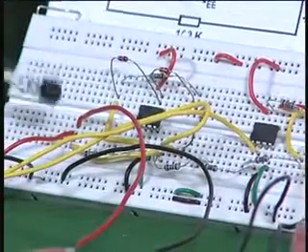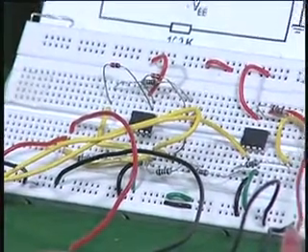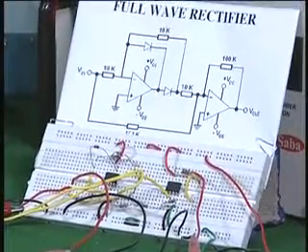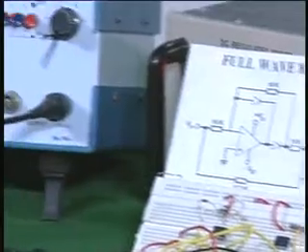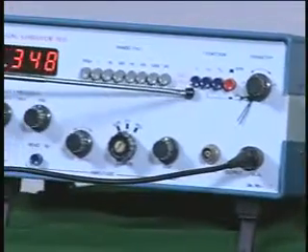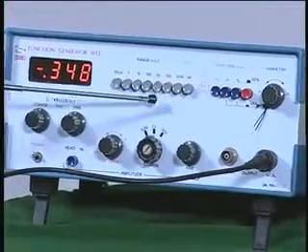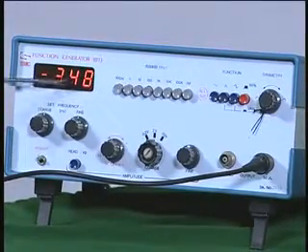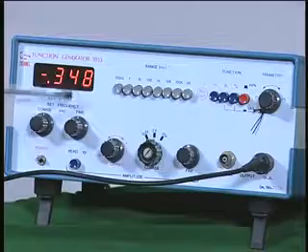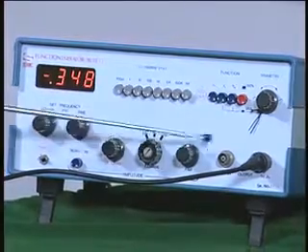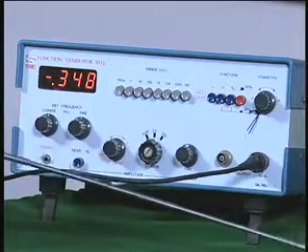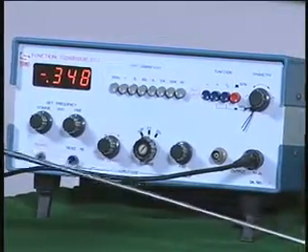So the circuit is exactly the same as what you see here, and I have now given the input from a function generator as before. You have the sine wave input and the frequency is around 1 kHz, and therefore I can measure the frequency and the amplitude over here, and now this input is given to the circuit.